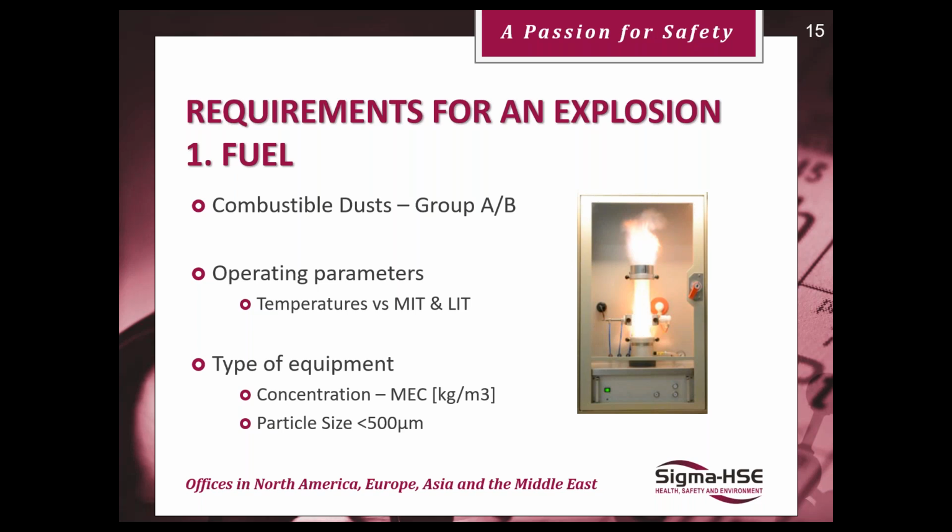And if it bursts into flame, as the picture shows, then it's a Group A dust, a flammable or combustible dust. If it doesn't ignite, it's a Group B dust. In a sense, that material's inherently safe, we don't need to bother about anything. But really, to create that dust cloud, just like with vapours, we need to be above the lower explosive limit, and between the lower explosive limit and the upper explosive limit. It's exactly the same with dust. We know it as the minimum explosible concentration.